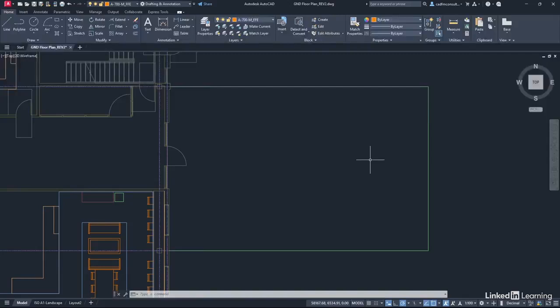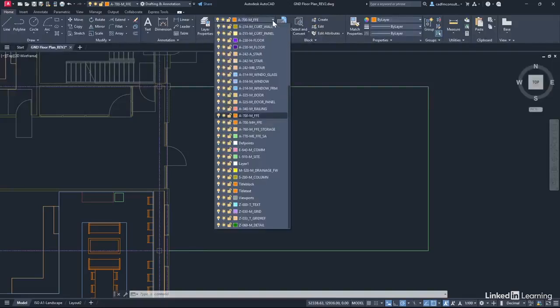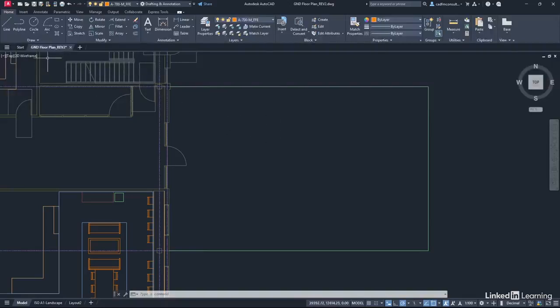So we're going to be taking a look at the rectangle command. Now, before we place the rectangle, just check your layer. Make sure you're using the A700M FFE layer for furniture. We're then going to go up to the draw panel here, home tab on the ribbon draw panel, and click on this little flyout here and select rectangle. Now, one of the ways of placing a rectangle is you can actually give it dimensions. Now, what we're going to do first, though, is pick a corner point. Now, I need you to pick a corner point just up past the door, about sort of there-ish. And as you come away, can you see it's asking you now for the two dimensions of the rectangle, horizontal and vertical.